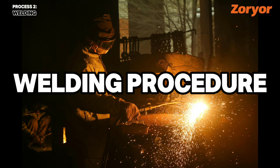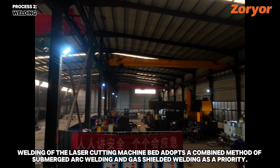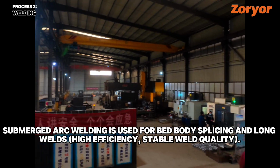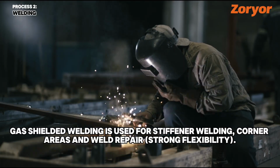Welding procedure. Welding of the laser cutting machine bed adopts a combined method of submerged arc welding and gas-shielded welding as a priority. Submerged arc welding is used for bed body splicing and long welds: high efficiency, stable weld quality. Gas-shielded welding is used for stiffener welding, corner areas, and weld repair: strong flexibility.